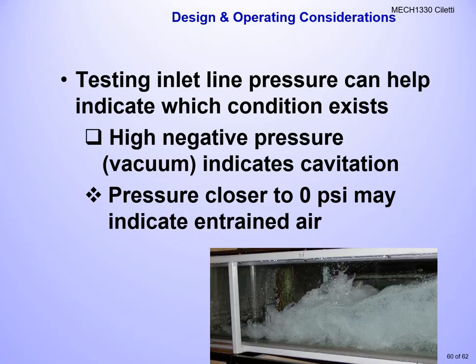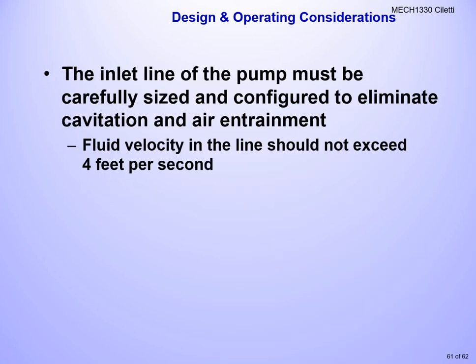So just be careful. We always want to test inlet line pressure. It helps indicate what conditions exist. High negative pressure indicates cavitation. Pressure closer to zero indicates that there might be entrained air, or an air bubble in the system. So just those two different things there.